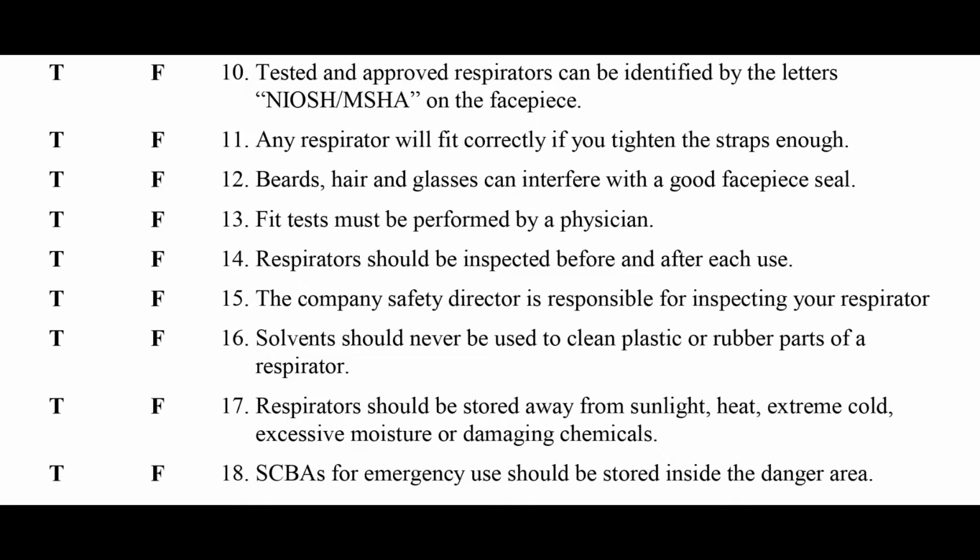That's true. Number 15, true or false? The company's safety director is responsible for inspecting your respirator. That's false. Number 16, solvents should never be used to clean plastic or rubber parts of a respirator. That's true. Number 17, true or false? Respirators should be stored away from sunlight, heat, extreme cold, excessive moisture, or damaging chemicals. That's true. Number 18, true or false? Scubas for emergency use should be stored inside the danger area. That's false. Scubas for emergency use should be stored outside the danger area.